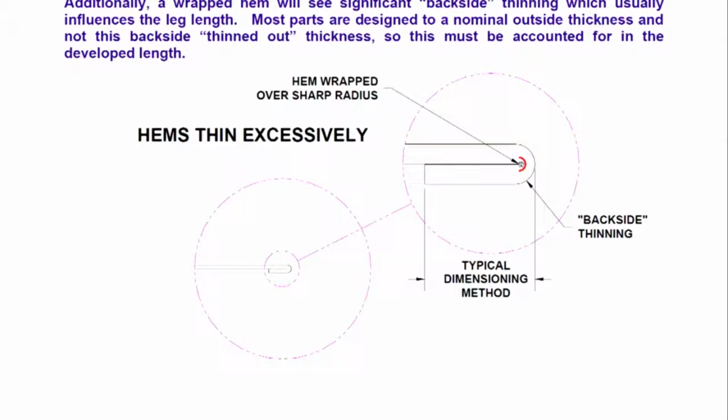At this point it will become obvious to you that if the grain structure of it, that is, if this is the rolling direction of it, it obviously bends easily. But if the rolling direction was this of the raw material, chances are it will break here. So, we are in trouble. Now, imagine you want it a little stronger, probably we would like to have one more limb this side. So, is it alright, can we make it with this? That point is where the designer will take a decision.